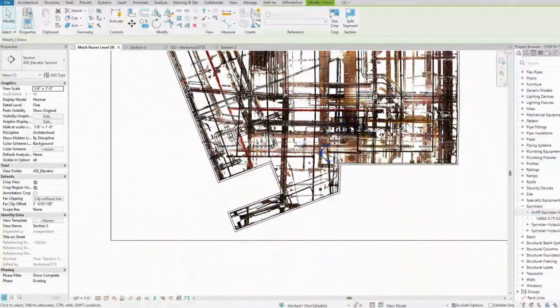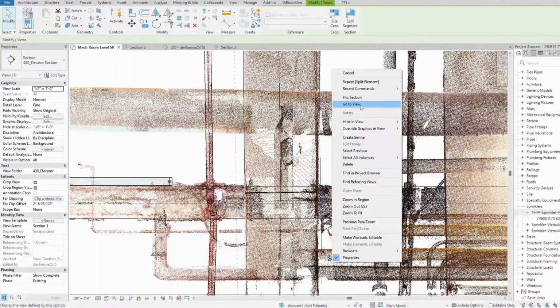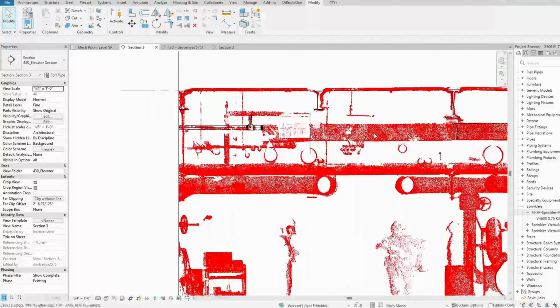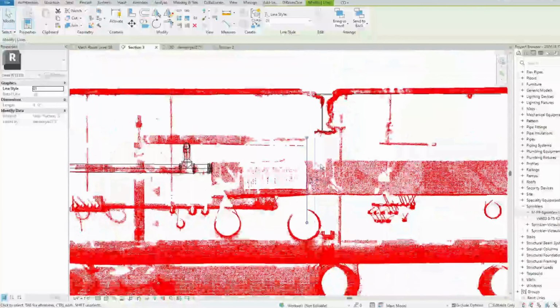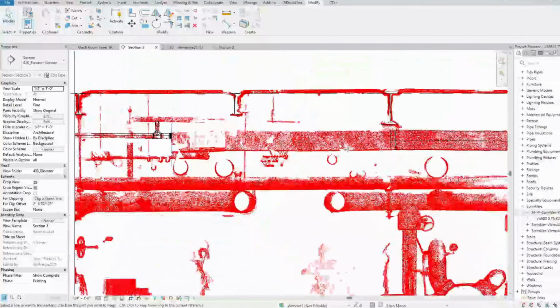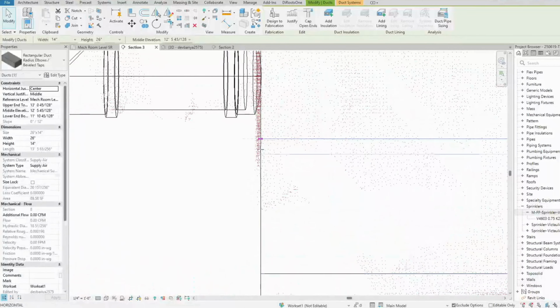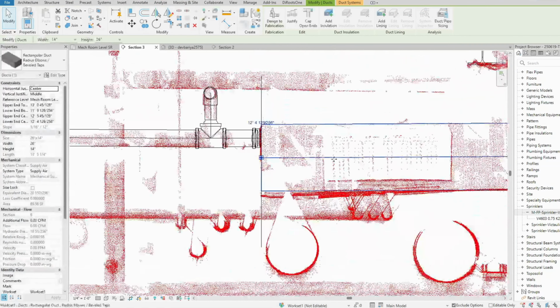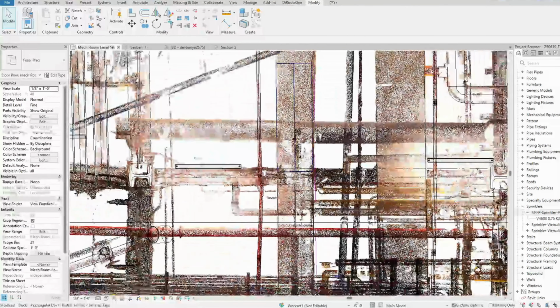And that brings us to the end of Part 01 of our Introduction to Ducting in Autodesk Revit. In this video, you've learned some of the most important basics to get started with duct design. We walked through how to set up the duct tool, how to draw a basic duct layout, and how to adjust key settings like width, height, and offset. You also saw how to click on any duct to view its properties, including system type, flow, and material, showing how smart and data-rich Revit really is.